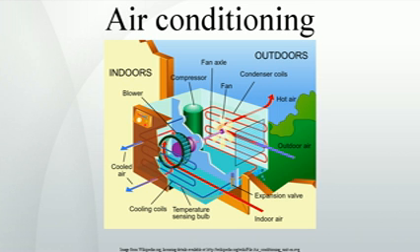Humidity control. Refrigeration air conditioning equipment usually reduces the absolute humidity of the air processed by the system. The relatively cold, below the dew point, evaporator coil condenses water vapor from the processed air, much like an ice-cold drink will condense water on the outside of a glass, sending the water to a drain and removing water vapor from the cooled space and lowering the relative humidity in the room.